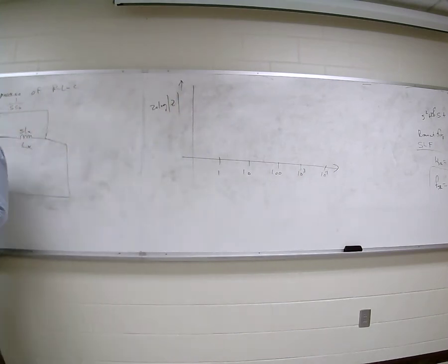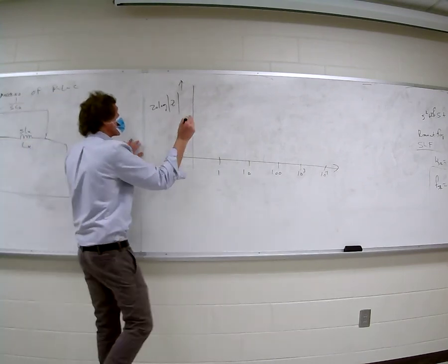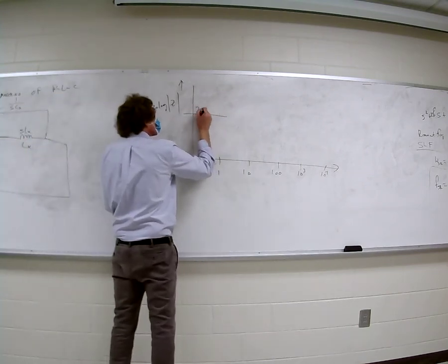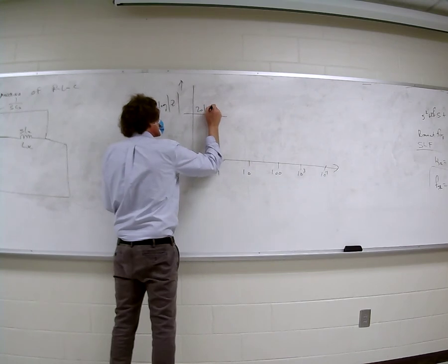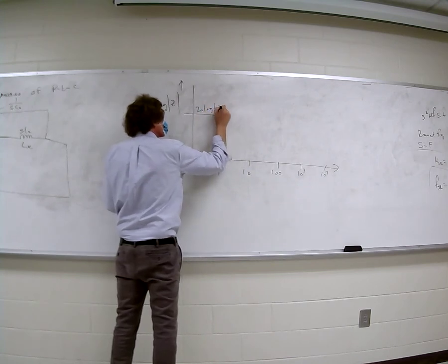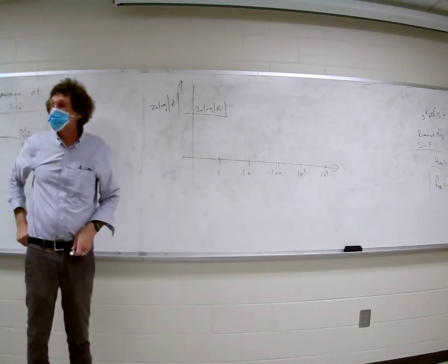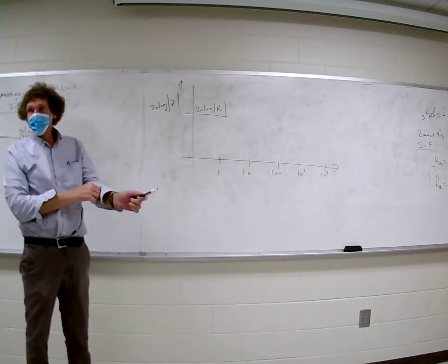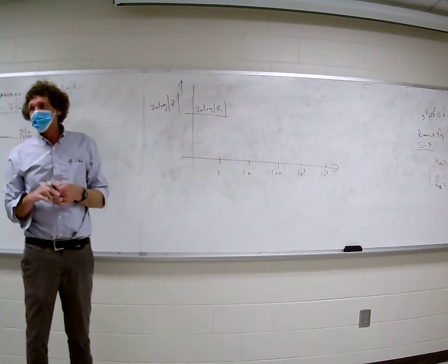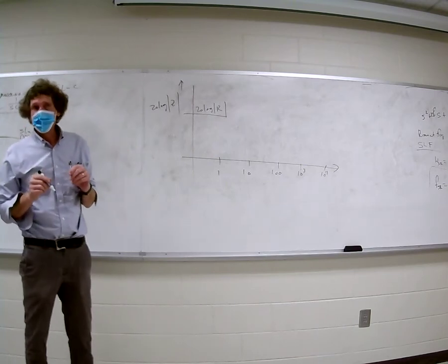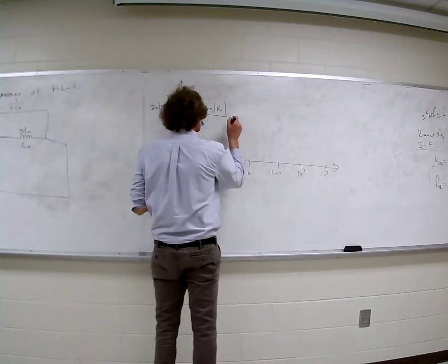Well, the impedance of a resistor is just R, right? So 20 times the log of R is where it starts. This is 20 times log of just R. This is typical, by the way. If you buy parts, they'll show this. They might show the actual plot. This is much more useful. And it'll be flat. It'll just stay that way.